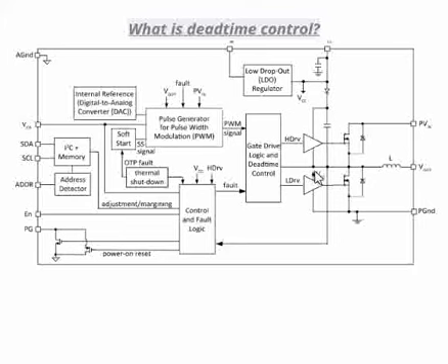Here, this block is going to generate the drive for the high side MOSFET and the low side MOSFET. So we know, right, high side MOSFET, you will have power supply connected and then the load is connected towards the source side. Whereas in the low side MOSFET, you will have ground connected to the source and then you have the output on the drain side. So there is a simple configuration where high side and low side MOSFET are combined together to form a bridge, right? This is a common configuration which we see in the regulators, the switching regulators basically.